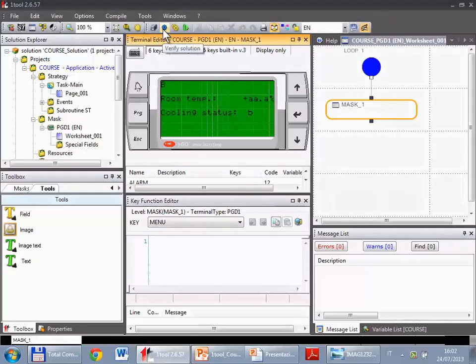After that, I introduce you to the other icon, verify solution. Verify checks for some mistakes, not all mistakes, but only some of them. So it could be convenient maybe every half an hour, 1 hour, 2 hours to click it just to see and fix some mistakes. An important thing is that that button, and also the one on the right, also executes the function on the left. So verify saves and verifies, as well as the compile, which is the function that we need, compile solution.